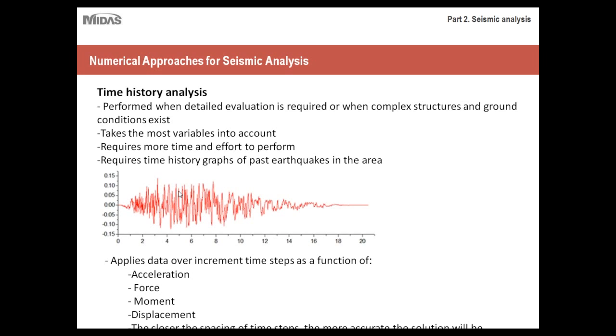But I just want to help you guys to become aware that time history analysis is especially useful for high loading or high seismic conditions. It requires more time and effort to perform, obviously, and it requires time history graphs of past earthquakes in the area. And here are the variables that are taken into account as far as your time history functions. It takes into account the acceleration, or the seismic acceleration of your loading. It takes into account the forces that are being applied to your structure, the moments, as well as the displacements.